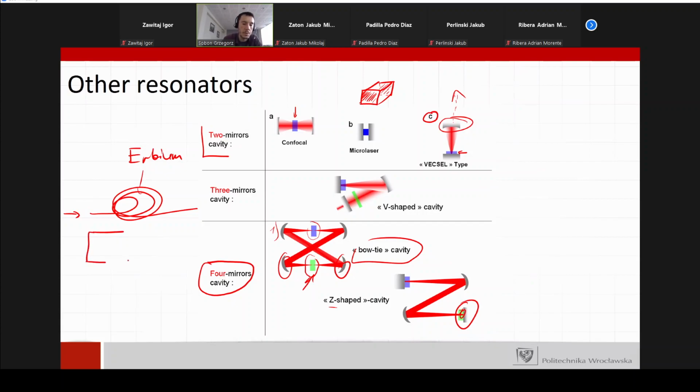to the optical axis. So this is, let's say, the image of the fiber. So we have the core and the cladding, and if we just cleave it perpendicularly, so we have 90 degrees here, such a surface will provide a feedback of 4% because of the differences between the refractive index of air and of the fiber, because air has the index of 1 and the fiber has the index of 1.45.